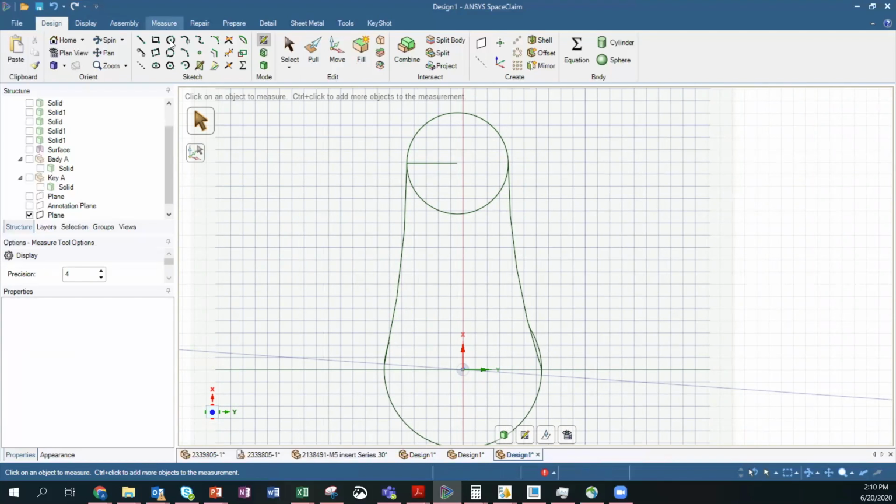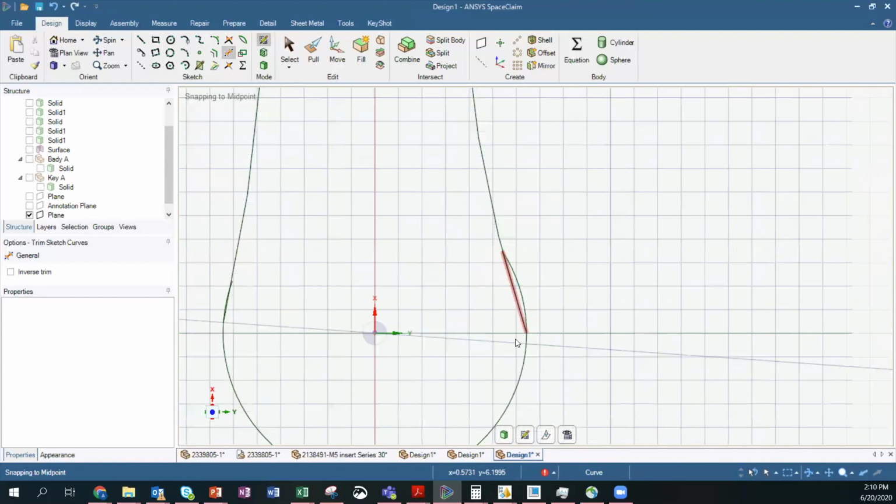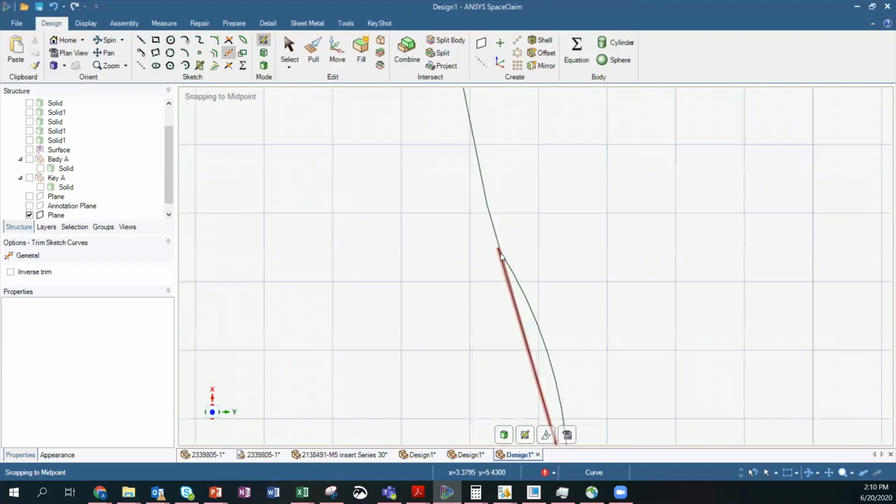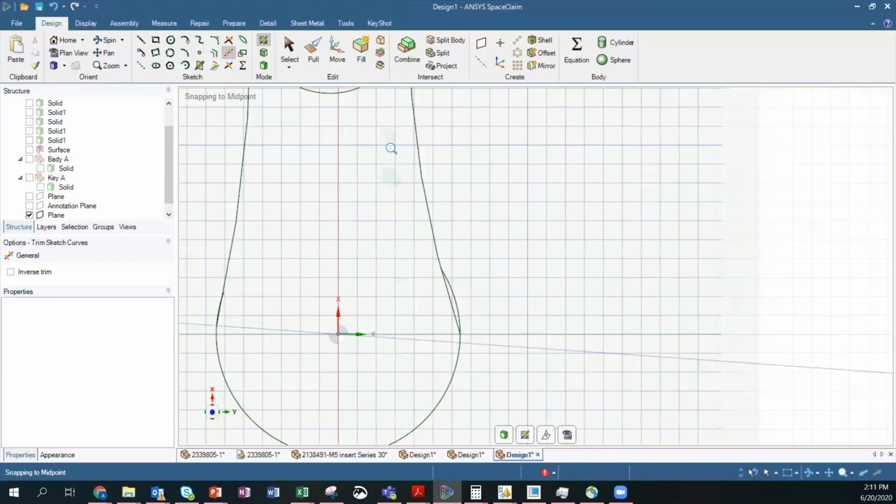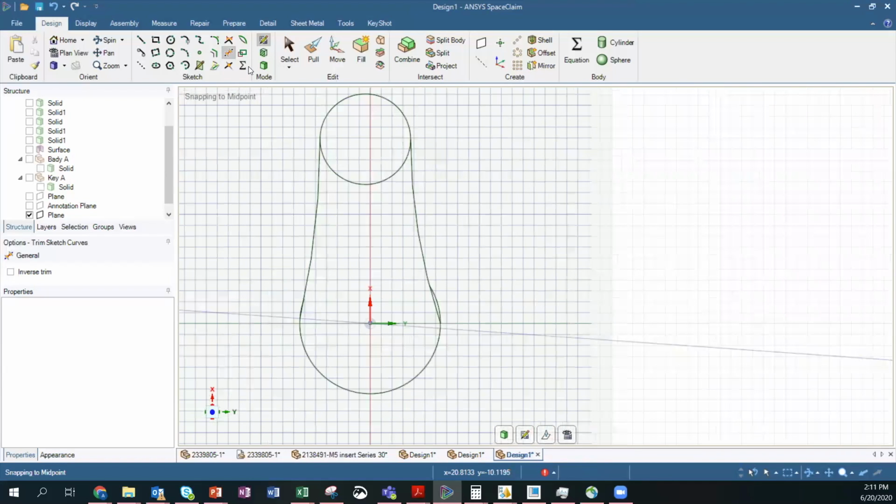make it tangential. There's a reason why I'm saying this, because right now from here, none of them are tangential, but this is even more harsh. There's a sudden turn. And when you make such a sudden turn, the part would have some residual stress. That point is a discontinuity, so it can be a little weaker. So we try to make it as smooth as possible.